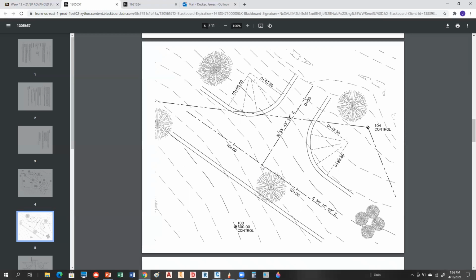We'll be able to sit here, backsight here, turn an angle and go a distance to set that point. Then we can just occupy that point, backsight that one, pop in a stake and turn delta over 4. So these are going to be real nice layouts. We're going to lay out the curve, and the 25-foot stations along both.